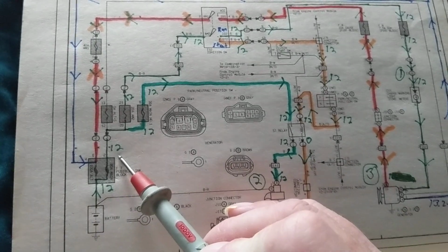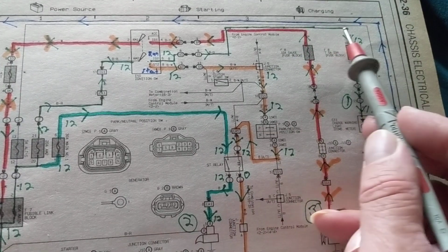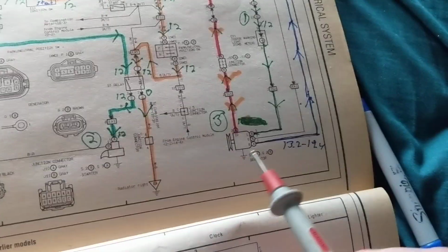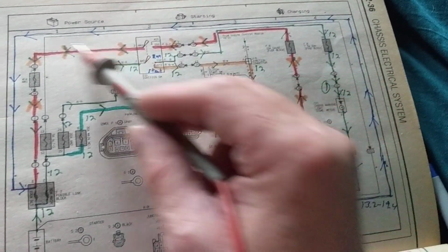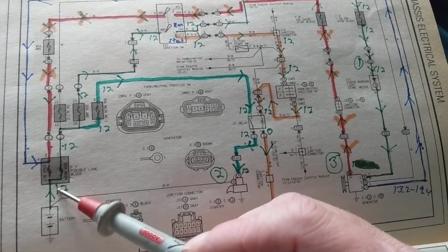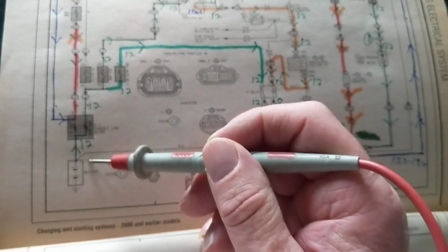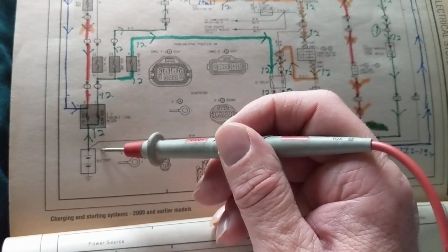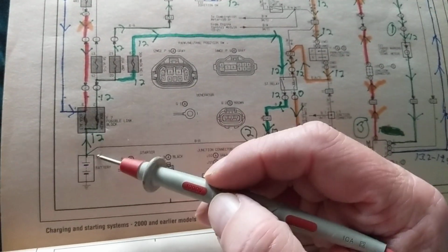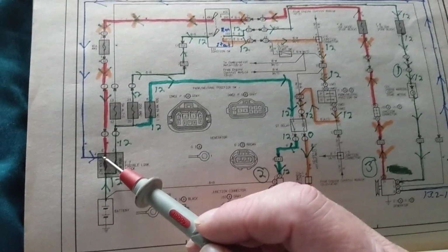When that happens, guess what happens? Here, I'm in the run position. Guess what? This will light. This indicator will light. Again, this is the output of the alternator going back here to this. This opened up. This is not getting 14 volts. What's it going to get? Whatever that battery charge was at last. Maybe it was 10 volts. Maybe it was 11 volts. Maybe it was 12 volts. Whatever it was. Now you're running on your reserve capacity of your battery. So it's not just the generator. It could be this also, the fusible link.